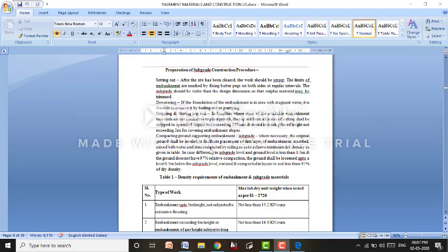In case of embankment construction or filling, you can't directly fill the soil to the required height and then compact, as it depends on the type of compactors or rollers you are going to use. If it is a static roller, it will not compact the soil thickness more than 100 mm, and in case of vibratory rollers, it will not compact more than 250 mm thickness. No, it will compact but not to the required extent.